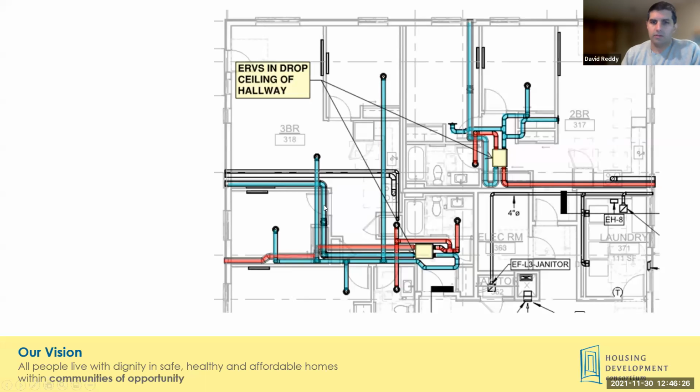So that illustrates one of the fundamental concepts of balanced ventilation, that it is providing distributed air throughout, but in this case, not exhausting the kitchen area. So this is not a distributed system under the 2018 Energy Code. This was permitted under the 2015 code, so that wasn't really a consideration, but this would not be a distributed system.